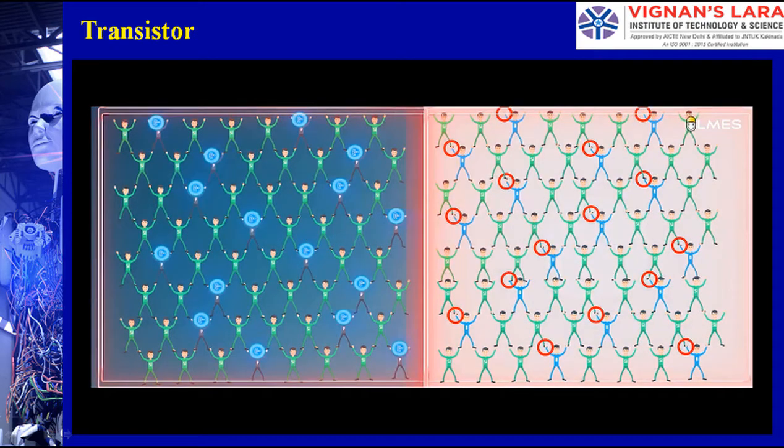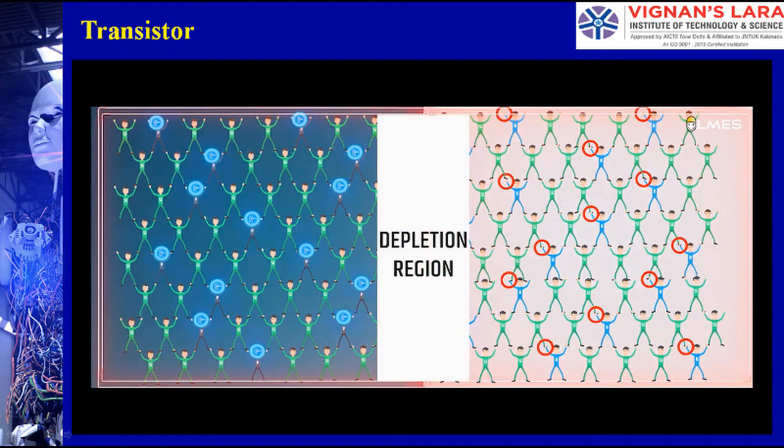On the boundary, the extra electrons from phosphorus will be attracted by boron and the boundary layers will each have equally 4 electrons. This zone is known as the depletion region. Now the n-type boundary becomes positive as it donates electrons. The p-type boundary becomes negative as it accepts electrons.